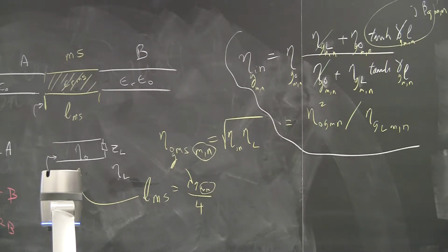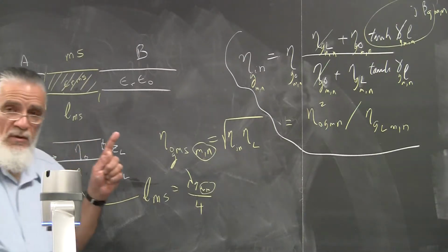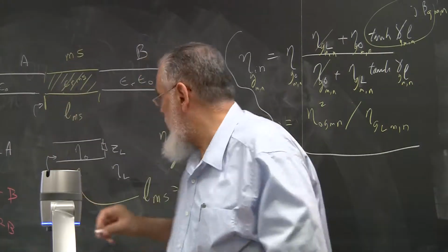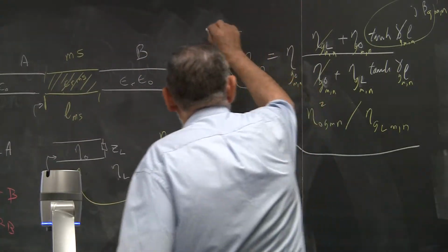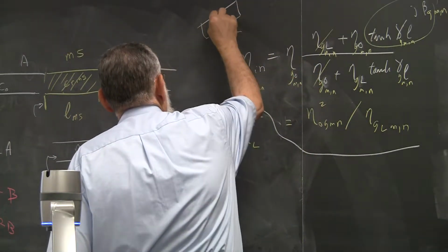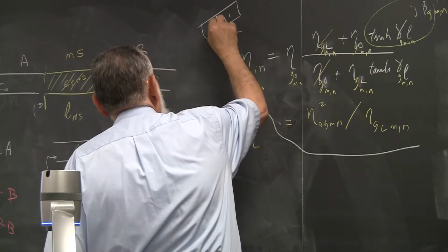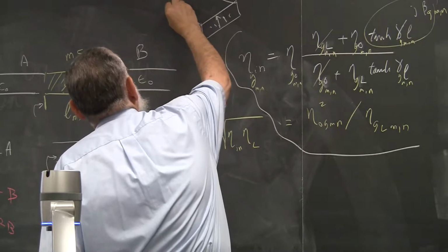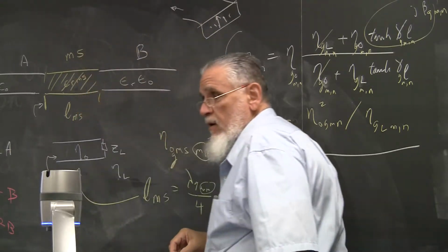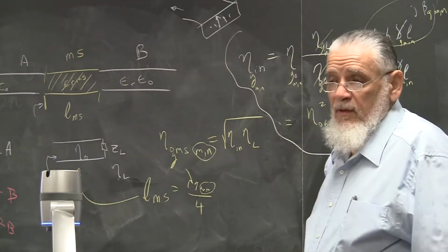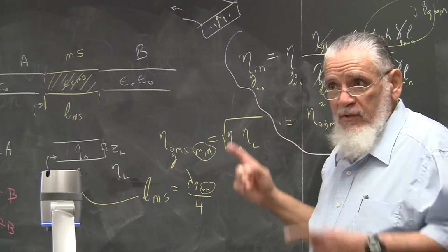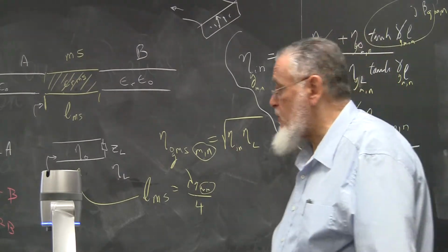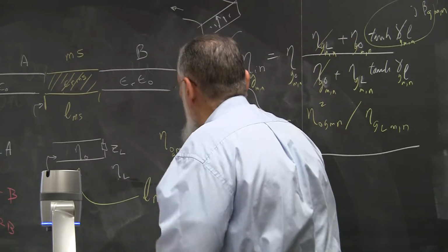In this case, that's your TE10. That's the same TE10. You want to make sure it's the same mode, because your field in the TE10 is going to be going this way, that's your electric field. And when it propagates, I don't want it to go eventually to a field that will have a TM, for example, because it's not going to be a continuous situation. Your field is not going to be the same.